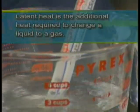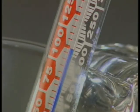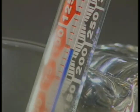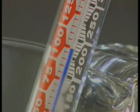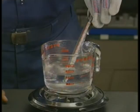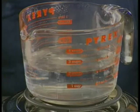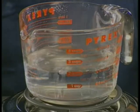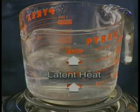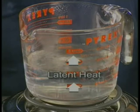Latent heat is the additional heat required to change a liquid to a gas. We know that water boils at sea level at 212 degrees Fahrenheit. We can measure that as we did before, and we know that when water boils, the liquid is changed to gas in the form of water vapor or steam. If we were to measure the temperature of the steam, it would be the same temperature as the boiling water, or 212 degrees Fahrenheit. The unseen or latent heat is the additional heat that excites the water molecules at the surface to move faster than those in the liquid and escape as steam.